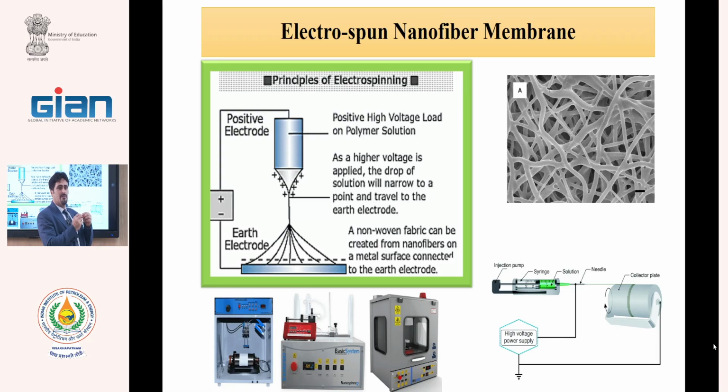But producing nanofibers from the needles that are used for microfibers is very hard. And production of needles with a diameter of nanometers is very hard. And in using these needles, because there are some gels in the polymer solution, the needles rapidly block.